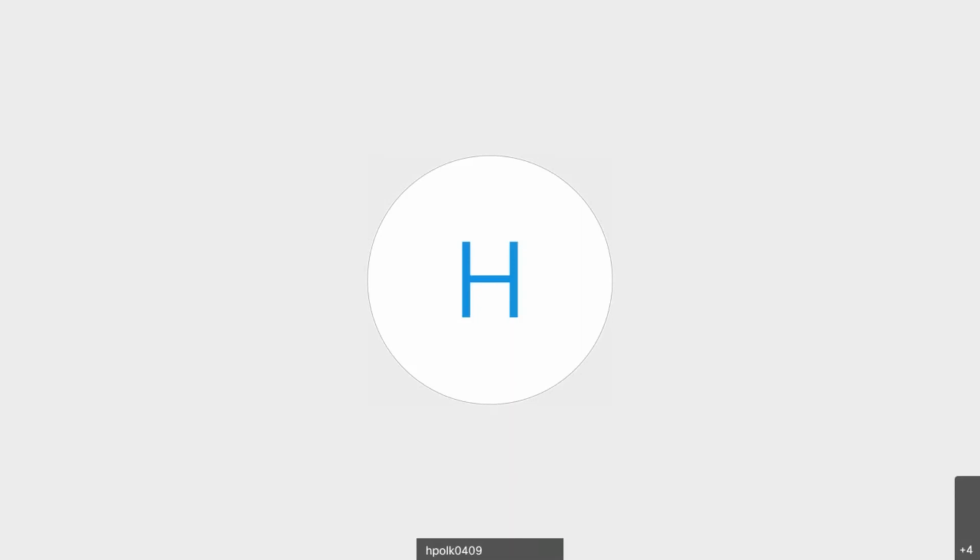I can take a stab at that. We have sonic technology where we can measure the depth of the mat at the back of the screed. We can use that same technology to measure the base in front of the screed, and we can do a differential between the two sensors to give you your mat depth. So that technology is available. It just hasn't been packaged correctly yet.